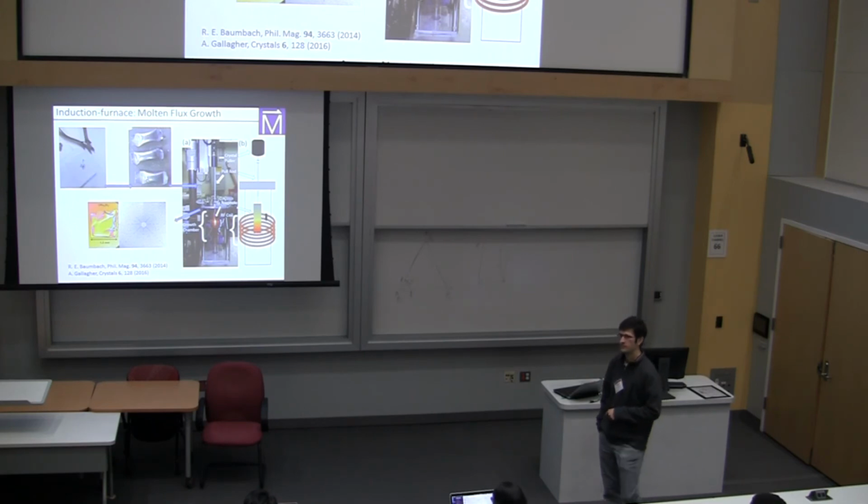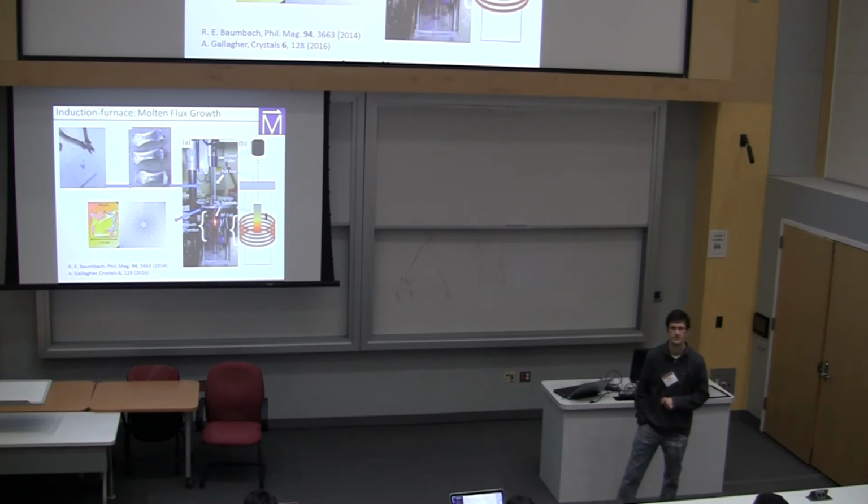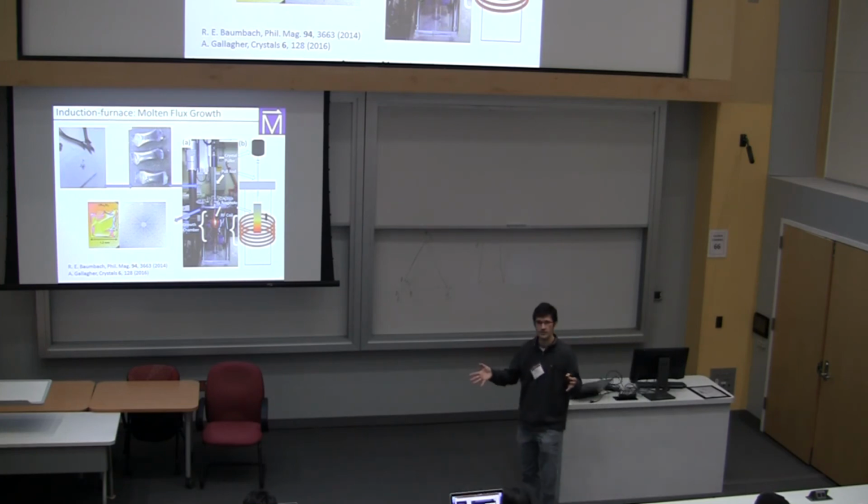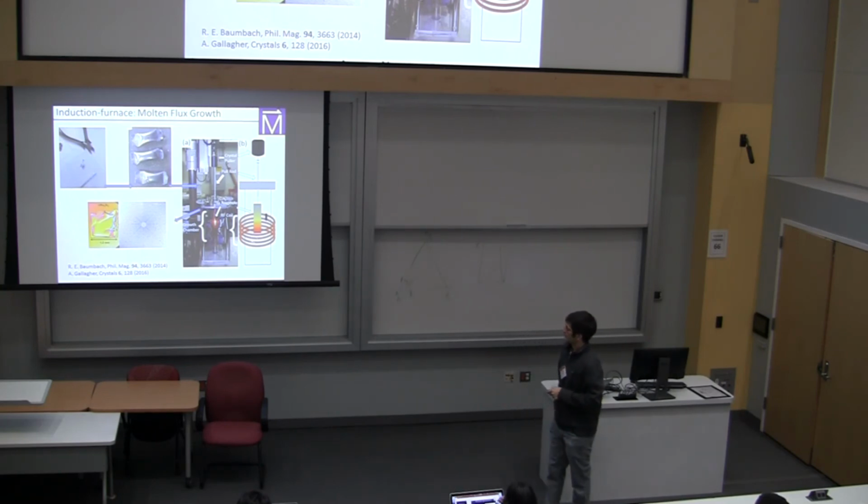And so now, in contrast to what you have in a box furnace where there's some temperature gradient, but not a whole lot, and you're ramping the temperature down by changing the temperature of everything sort of all the same, we're making this temperature change in a crucible that has a pretty strong temperature gradient on it, right? I think that's helpful for crystal growth. At the same time, we're stirring this melt like crazy.